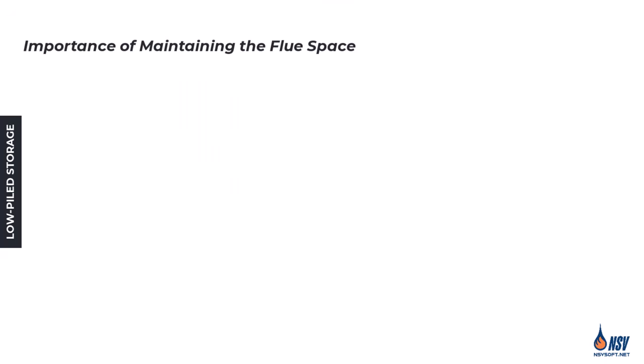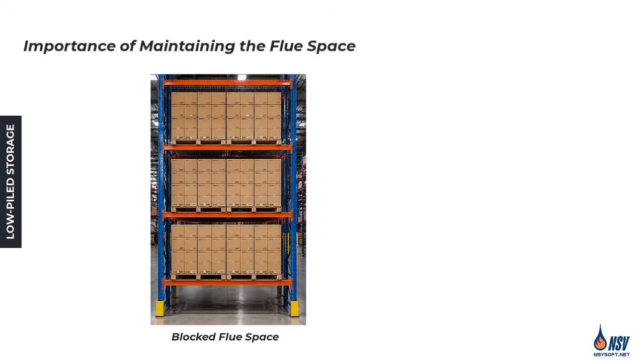However, the physical structure of the rack is only part of the equation. We must also consider how we place our loads onto them. Even if we use wire mesh shelving with more than 50% open area, the boxes or pallets we place on top will physically block those openings. Because the load itself blocks the water, the gaps between the loads become our primary pathway for fire protection.